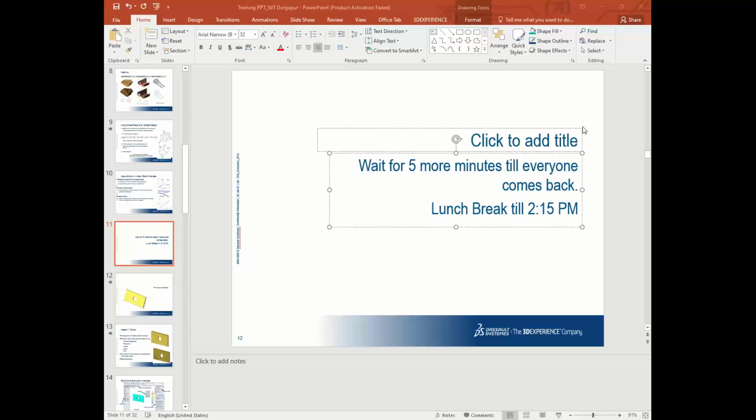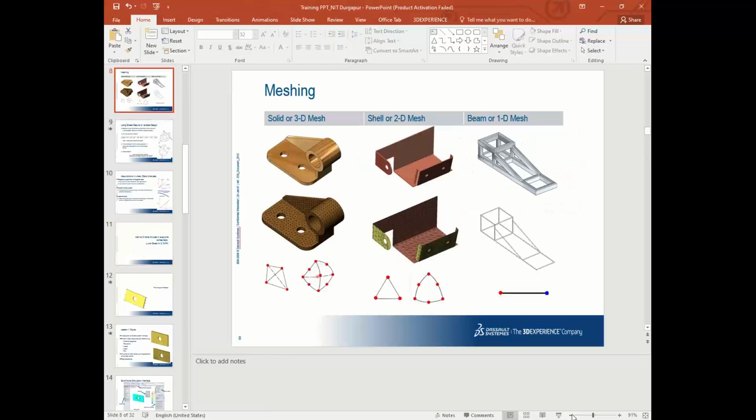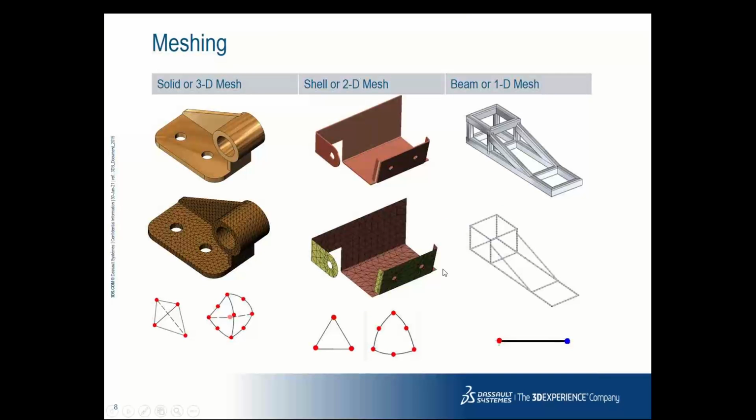We have seen what exactly a mesh is, what elements are, what nodes are, and what the different types of elements are. There may be solids, shells and beams. We also saw the subtypes of those elements and how they affect your simulation results. There may be linear, that is draft quality elements, and parabolic or high quality elements.